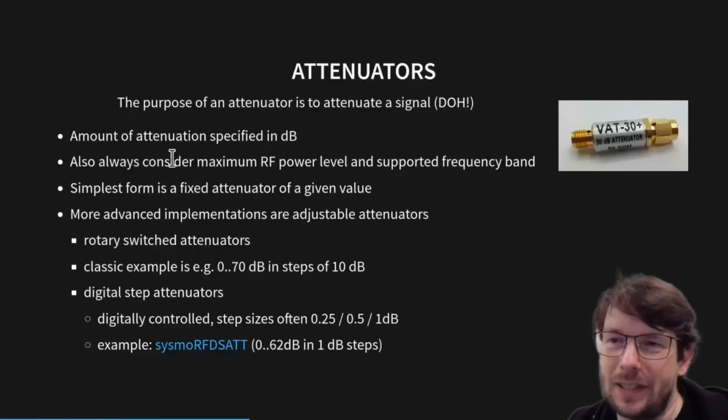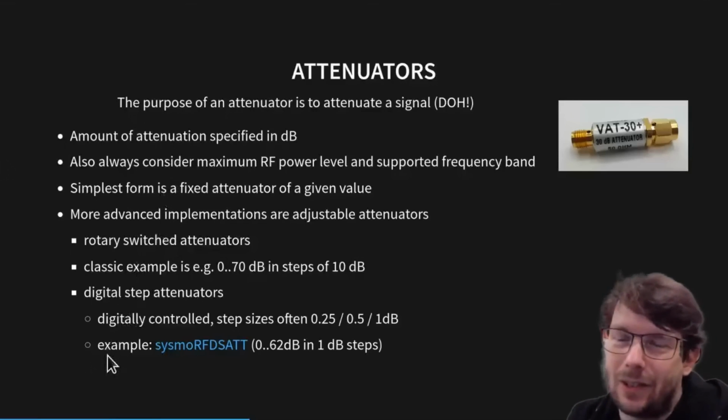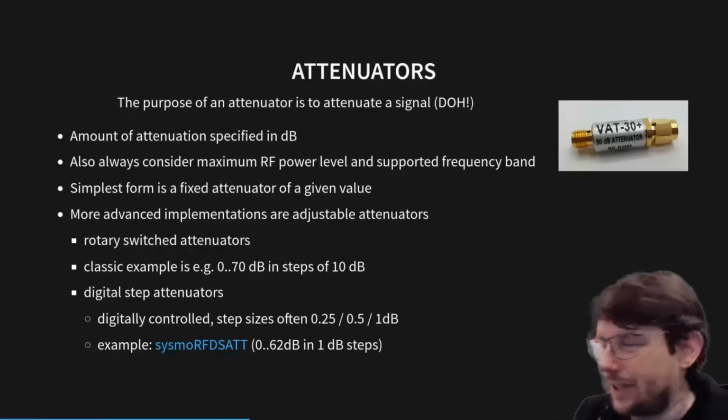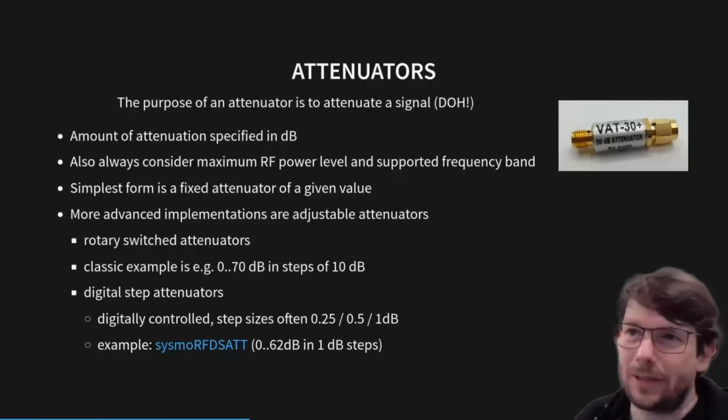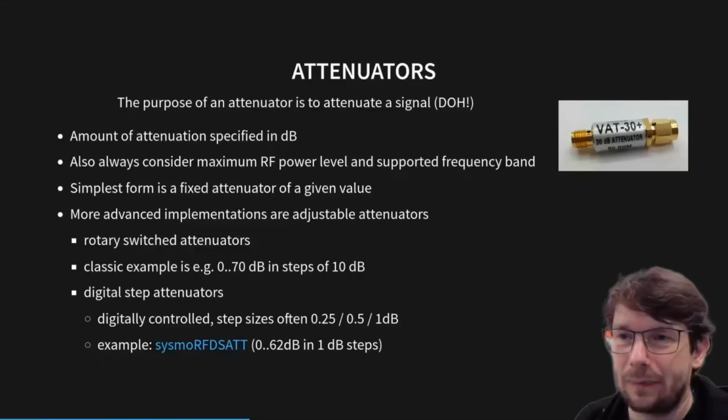The other option is digital step attenuators. These are basically electronic. So all of the devices up to the rotary are completely passive. They don't need supply power. They're pure passive parts, RF in, RF out. The digital step attenuators then need power supply, and you have some kind of digital interface, such as a serial port or parallel pins, and you can then adjust, with digital control signals, the attenuation that they achieve.